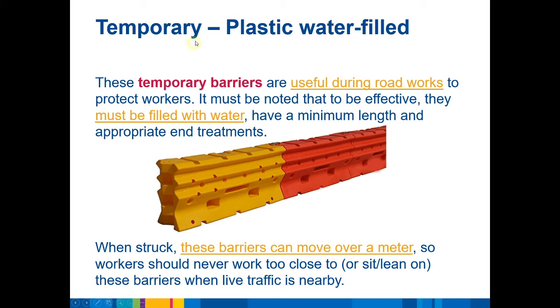Now we enter a class of barriers which are temporary. So we've got temporary plastic barriers that are water filled. These temporary barriers are very useful during road work or for other temporary traffic management. If you see on Gilly Street at the moment, at the intersection of Gilly Street and Gregory Street, there are a number of temporary water-filled barriers that have been used there. These barriers basically control movements into Gregory Street in a safe manner while the Regional Roads Victoria upgrade is being built. So the City of Ballarat wanted Gregory Street open, and the temporary barriers were a way to do that.